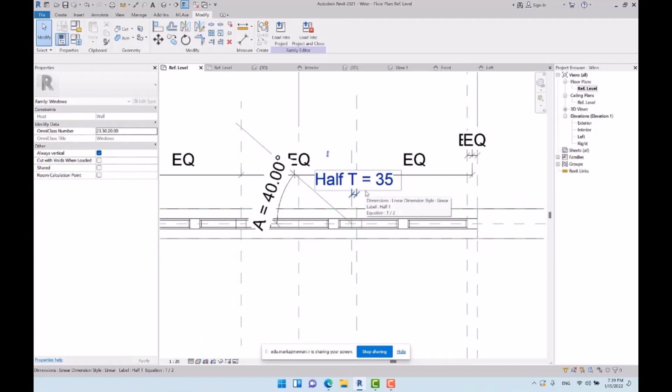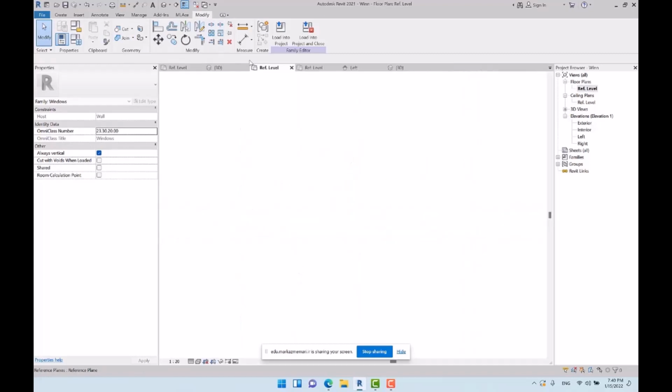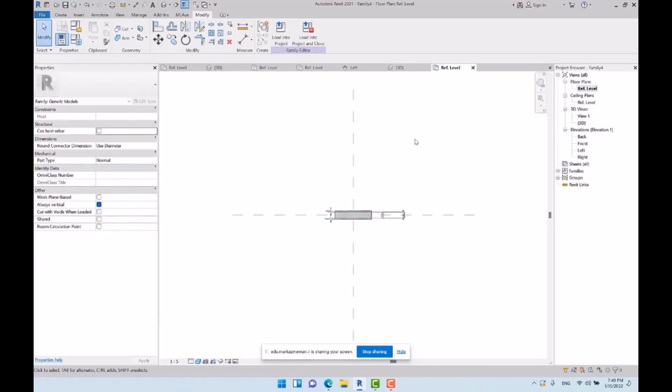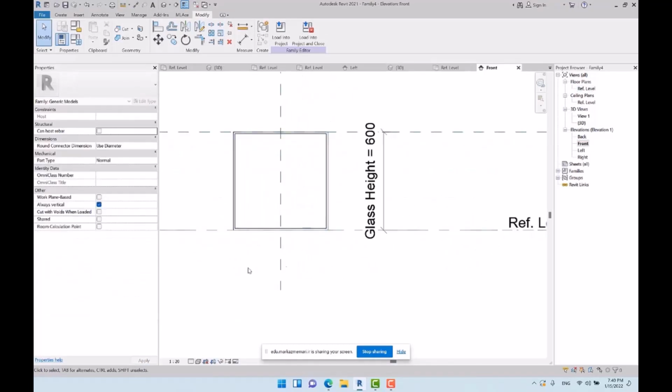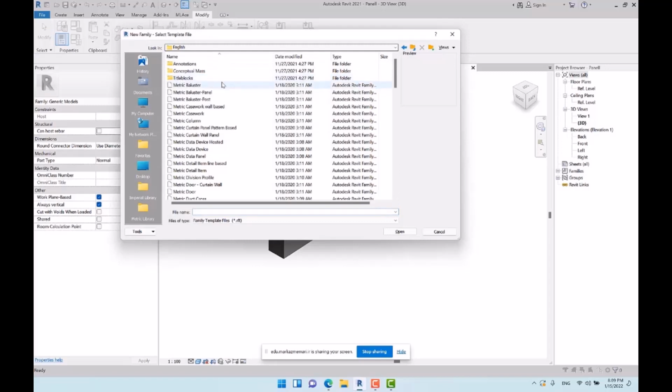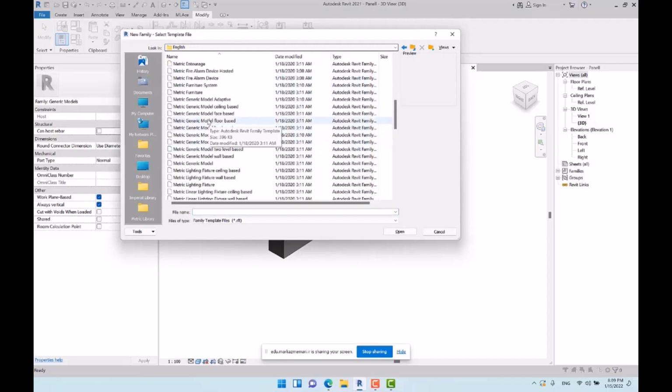Now at this moment, I'm gonna connect another panel to this reference line as the door of the window. Or in other words, I wanna assemble a panel on the line. Here we can use the previous family template file in order to not create a new one and save our time. If you want to connect these to the reference line, I should load it into a face-based family template file. I will talk about the face-based families later.